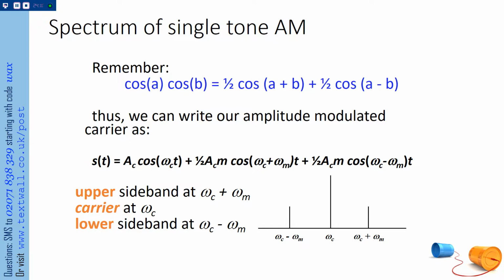What are we doing inside an AM modulator? We're adding DC, scaling a little bit, then multiplying. So the 2 operations which will reflect themselves in the frequency domain, which will change the shape of the spectrum, are adding a DC component, and then multiplying. What does multiplication do to a spectrum? If I take a signal, I multiply it by a cosine, what does that do to the spectrum?